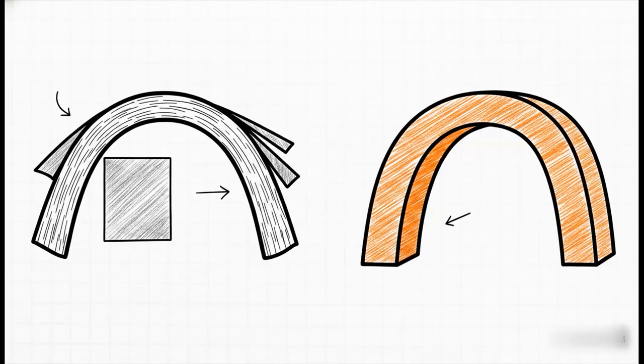To really grasp what sections remain plane actually means in the real world, just imagine a really thick paperback book. If you bend the book, the pages fan out to accommodate the curve, right? They rotate relative to one another. But if you take any single individual page out, its surface is still completely, perfectly flat. Well, in our beam, the cut faces stay perfectly flat even as the entire object curves under massive loads.